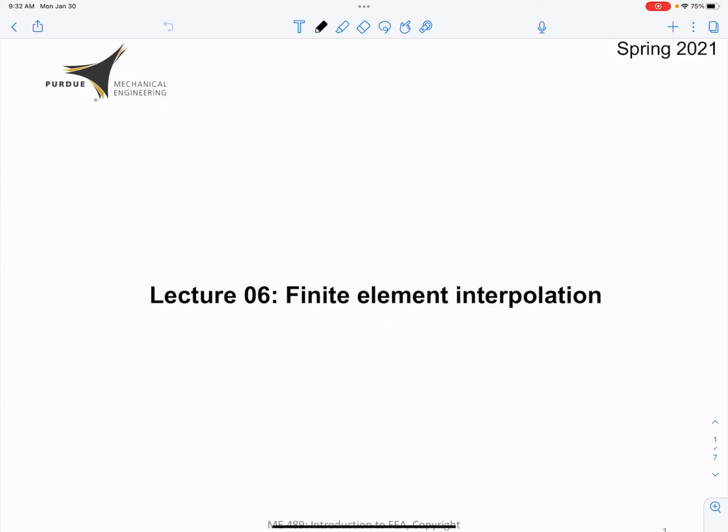The default in Abaqus, if you just put stress, it will do the von Mises stress. But that one is not really relevant for the trusses. The one that is relevant is S11, so the axial stress for the trusses. Or for displacements, maybe one of the displacement components is the most relevant, so you should plot that one and not the magnitude, for instance. So just keep that in mind.